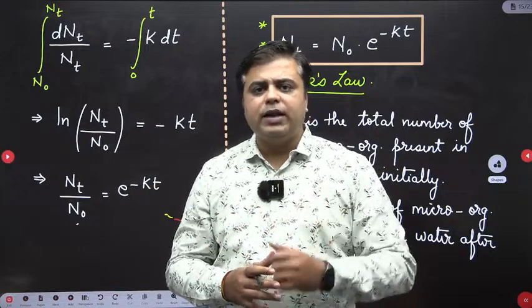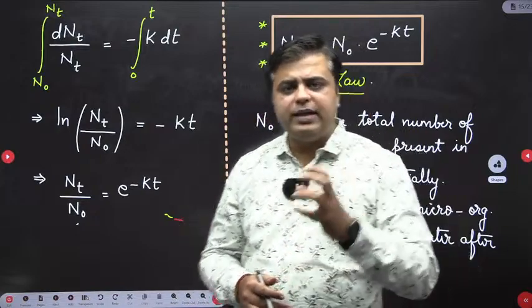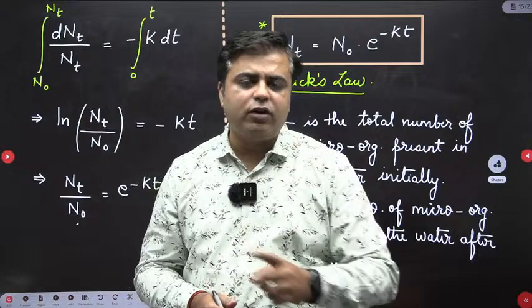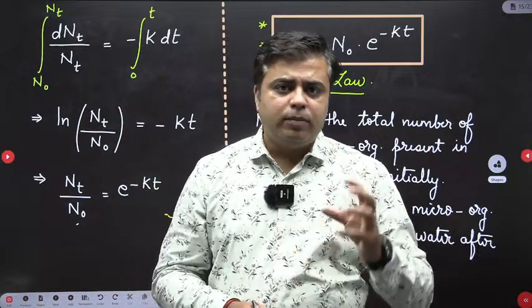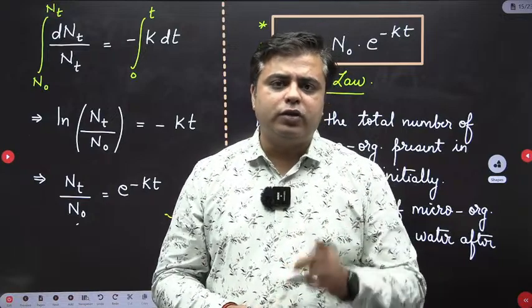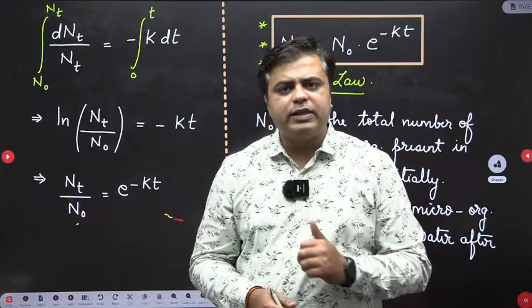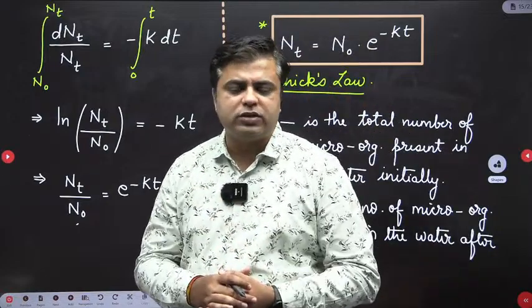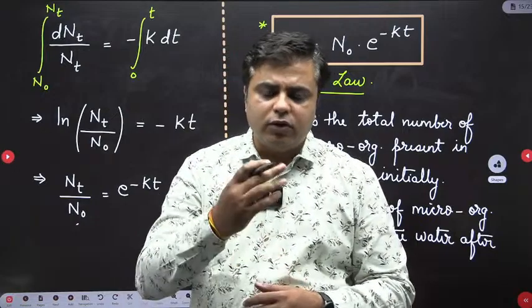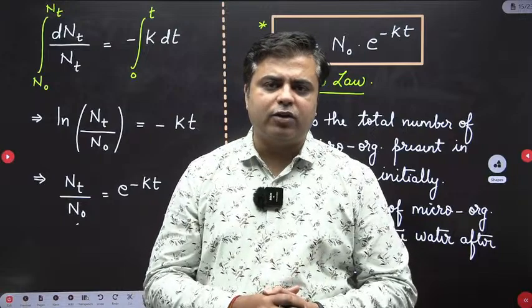We have seen the minor methods of treatment. First one is treatment with ozone. So ozone, being highly reactive in nature, destroys the cell wall of the microorganism, leading to the killing of microorganism. Because of high reactivity of ozone, it cannot take care of future recontamination. Second, treatment with KMnO4. So KMnO4 basically increases the permeability of the pores present on the cell wall, due to which all the essential fluid flows out and leads to the killing of microorganism.